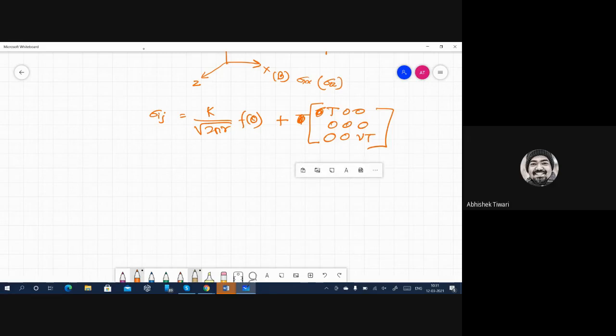So in the thickness direction, in the ZZ direction, you have Poisson's ratio into this amount, which will be applied in the thickness direction. So that stress. And you have 1 into T, which will be coming in the sigma XX direction. So there are only two components. One is out of plane and one is in plane. And the rest of the things remain 0. Okay. So this term defines constraint. Nothing to bother about it.